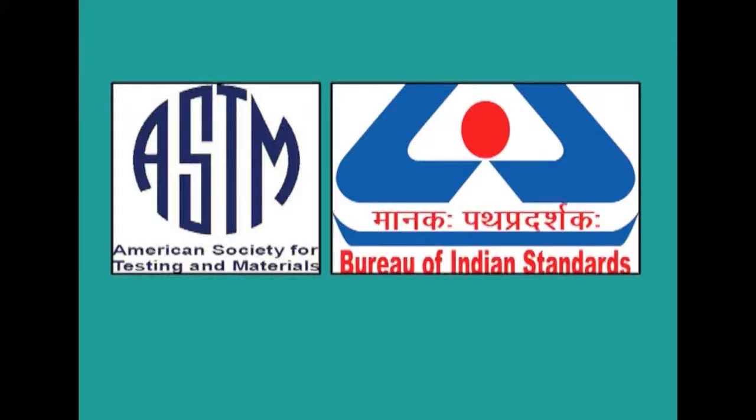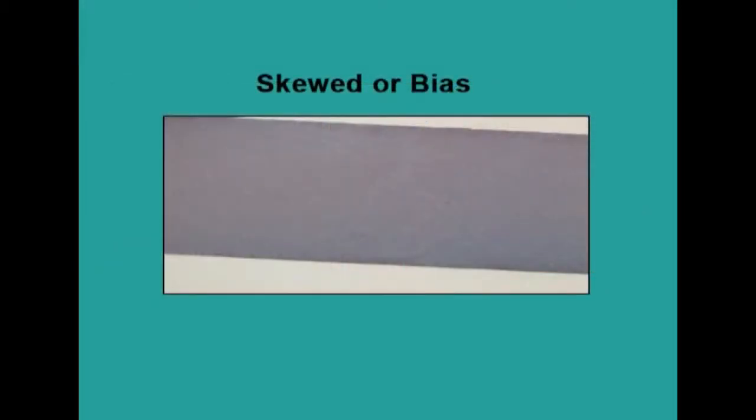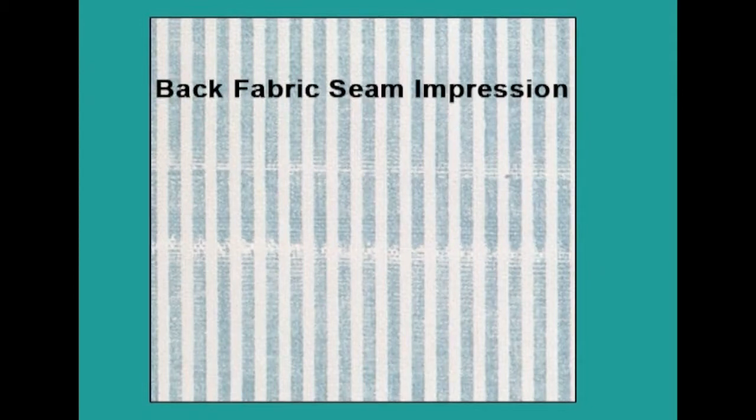So, having known the yarn defects, let us see the fabric defects that are identified by American Standards for Testing Materials, Bureau of Indian Standards and other standard institutions. One of the defects is skewed or bias, a condition where filling yarns are not square with the warp yarns on woven fabrics or whose courses are not square with the wale lines on knits. It is considered as a major defect. And back fabric seam impression, in this case a backing fabric is often used to cushion fabric being printed. If there is a joining seam in the backing fabric, an impression will result on the printed fabric. So, this may be considered sometimes as major or sometimes as minor.